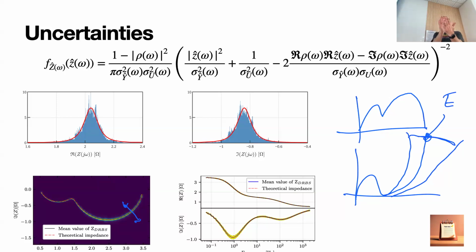And when you compare these two values, if we have something like this, the change is not statistically significant. But because now we have this distribution, we can quantify it. We can say that, look, this impedance changed, but the change is within the noise levels that we have. We should not consider this as a fault, or at least with our instrumentation, we cannot. We need either more precise instruments, longer measurement time, whatever. With the constellation that we have, it is within expected values, and we can do this.